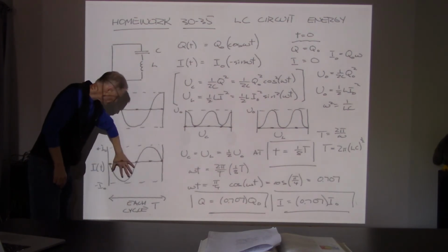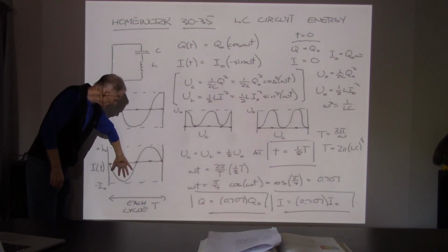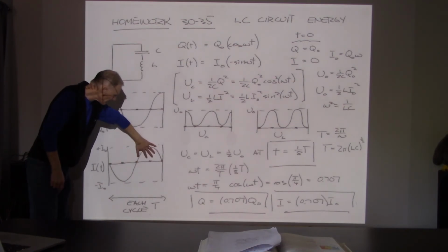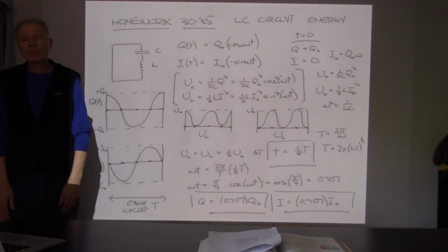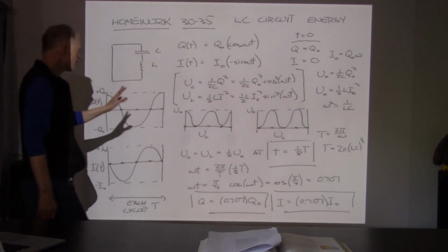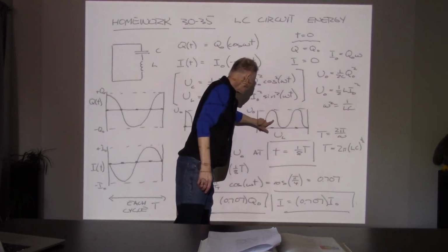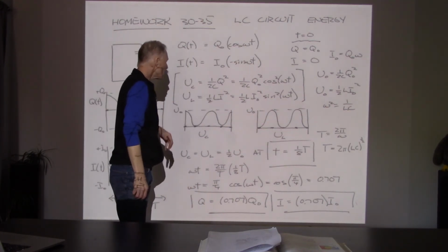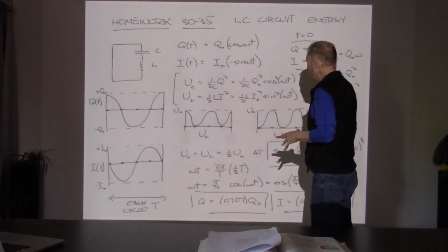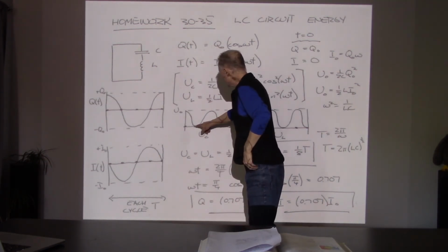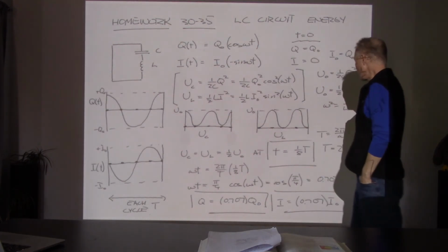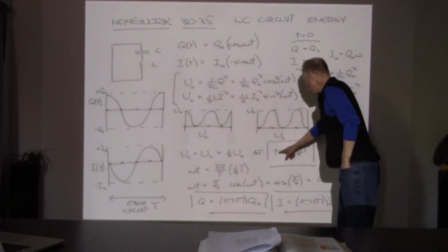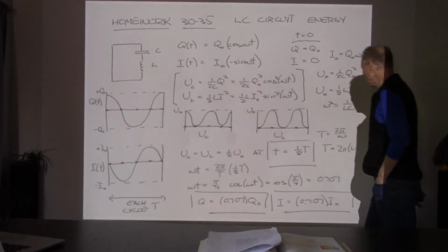So I'm going to get an energy peak here in my inductor, and I'll get an energy peak here in my inductor. So that's going to depend, we're going to end up with, rather, that there's two peaks of energy for each cycle. So that means that the energy, let's see, that's 1/4 of a cycle when the energy has gone to 0. Halfway down would be 1/8 of a cycle. And so I'm going to write that T as 1/8 of a period.